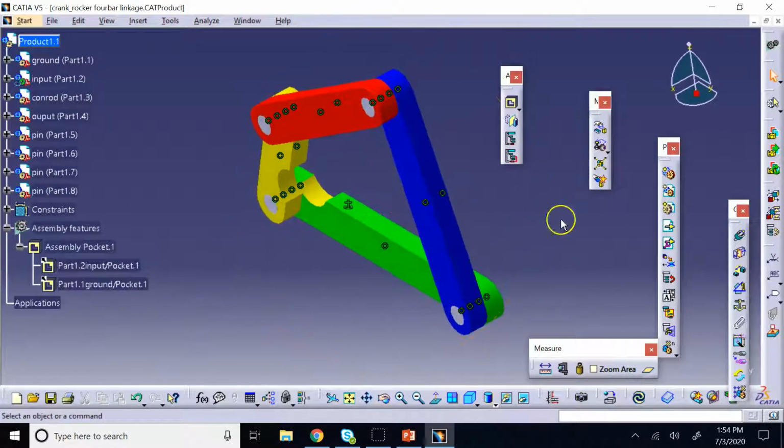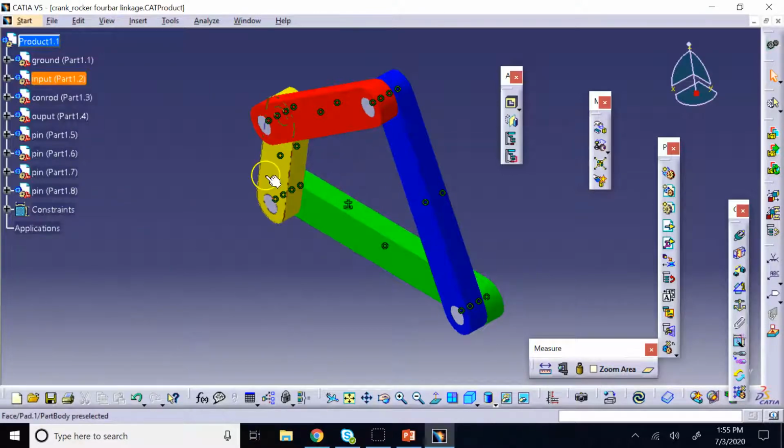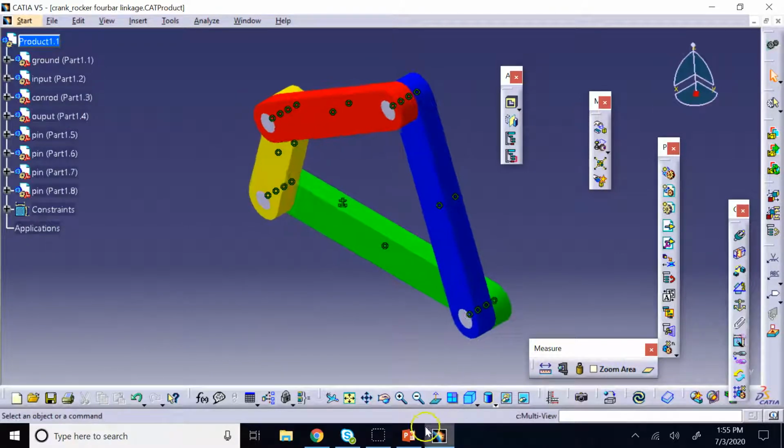Okay, so this is called an assembly feature. And as I said, only these 5 commands can be applied to all or a few members of the assembly. Okay, so that is an interesting thing by itself. Instead of going in each one of them separately and cutting them, you can do one sketch and then apply it to the whole assembly.